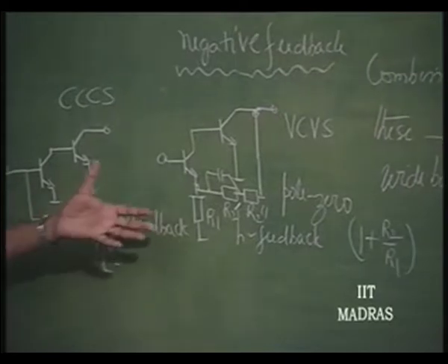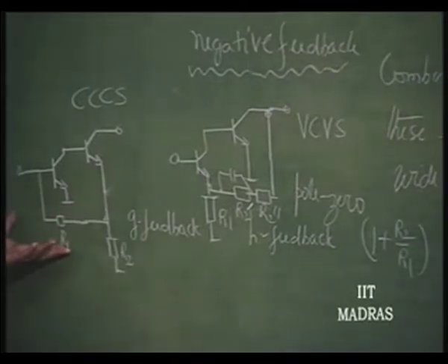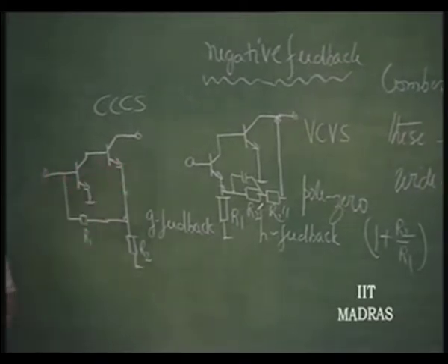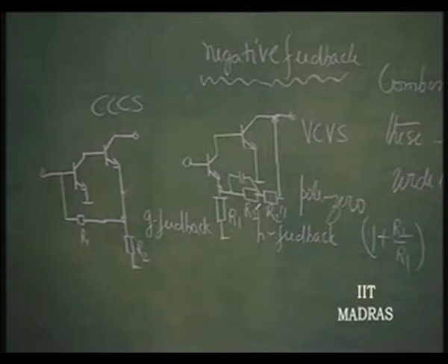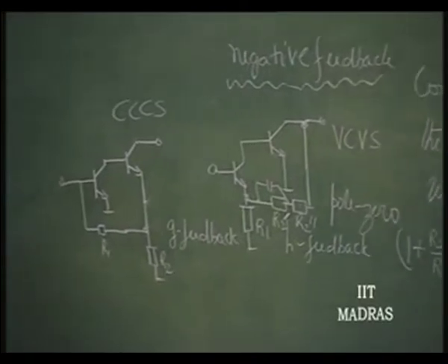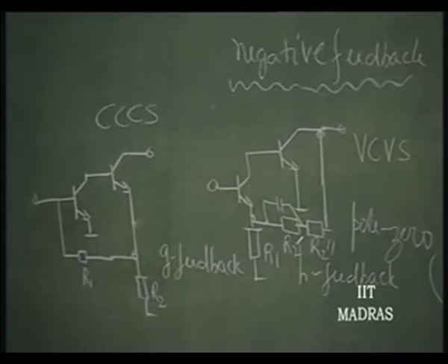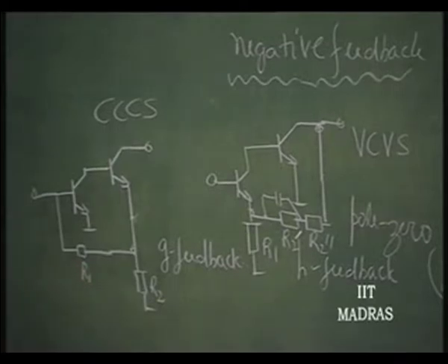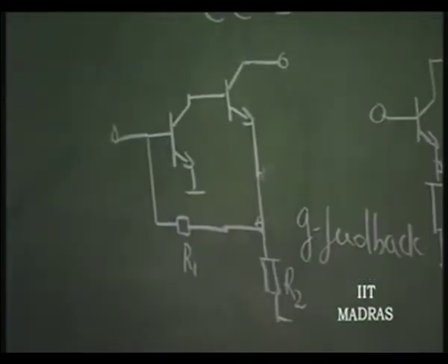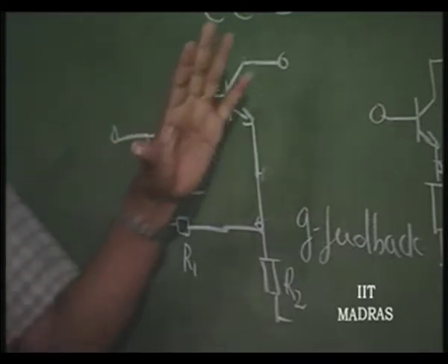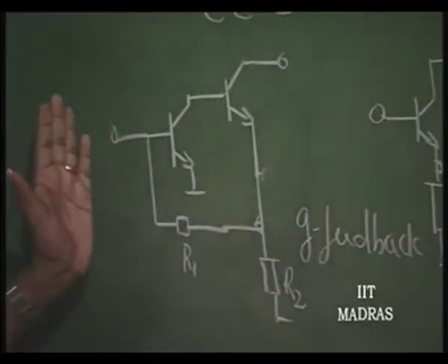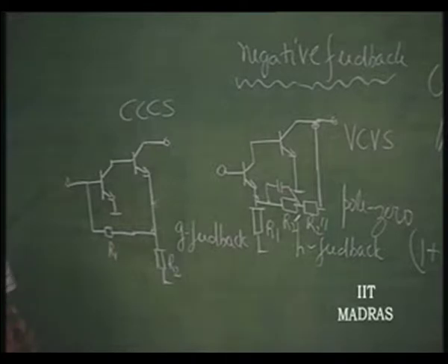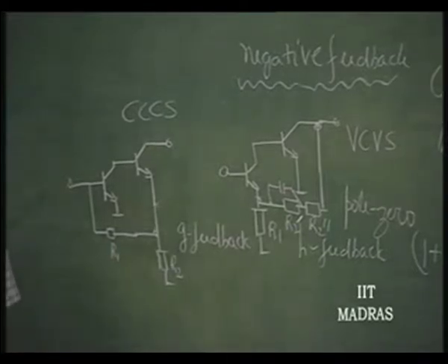Beyond these 2 stages, normally, that means connecting 3 amplifier stages, it is very difficult to make it work suitably as a wideband negative feedback structure, because invariably the oscillations persist. It is very difficult, because the number of time constants increase to 4, minimum 4. So, it is enough if we discuss all these amplifiers, which we have already done, as wideband structures. These wideband ICs are also available in the market as video amplifiers.